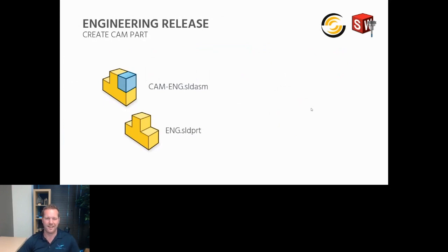It's kind of a touchy subject when you're giving people permissions to edit the native file, you could say. And so, creating a new file gives them some abilities with assembly operations or assembly features to remove material for, say, if you had an anodizing that added thickness, well, you would have to have your original start part reduce the thickness of that component to whatever the thickness of that anodizing is, so that when you go through that anodized process, the engineered part and the final part dimensionally match.